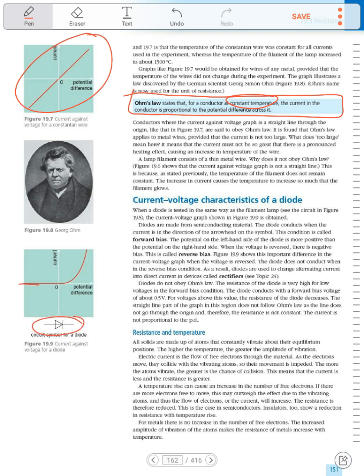The diode allows the current to flow through it only at a specific voltage. Before that point, no current passes through it, so it's zero, which is a backward bias. At a definite voltage it starts to allow the current to move through it. So the diode is a rectifier. It allows the current to pass in one direction only.